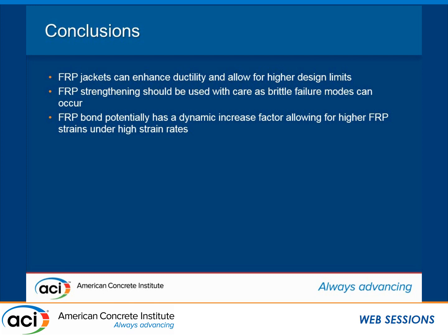Number of hoop wraps, how do you calculate? Yeah, so I don't have this one in here, but the number of wraps for ductility can be based off of a performance-based seismic design standard. At least this was where we sort of left this particular project. So based off of that, if you take the relationship between how far you want to drift and the level of axial load, you can then compute, with a built-in confinement model essentially, it's a very empirical equation, the amount of internal transverse reinforcement that you need in the hoop steel to gain that ductility.